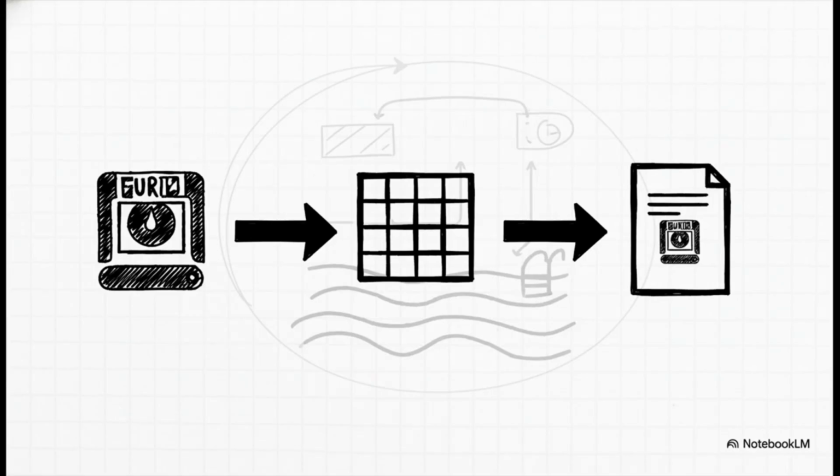Why the separation? Well, you have articles like Class 2 and Class 3, remote control and signaling circuits, which is Article 725. Those systems are designed to inherently limit the energy available. They're power limited by design. Exactly. And they need separation from the general branch circuits to prevent a short from injecting dangerous amounts of energy into equipment that just isn't rated for it.